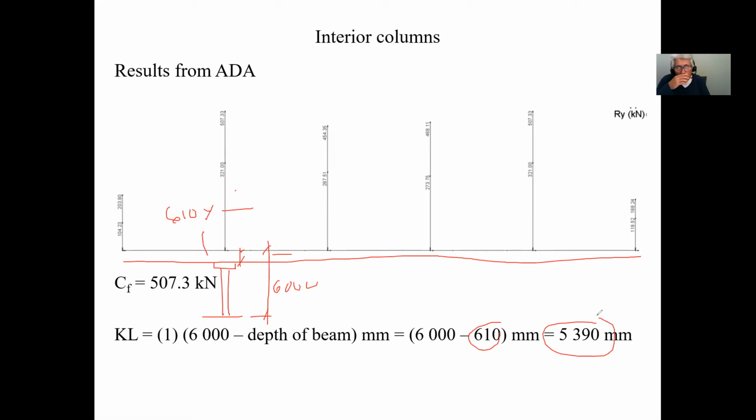And it could even be lower depending on the sloping that you have to create on your roof. But this would be the guaranteed maximum height of your column. Okay. So does everybody see that? The fact that on the drawing, when we show the column going like this and we show that the beam is going over it, that means that the column is below the beam. When we draw this like this, that means that the column is going to be at the same height as the beam, and the beam is going to be attached to the side. So that's the difference when you show this on your drawing and you show this on your drawing. Okay.